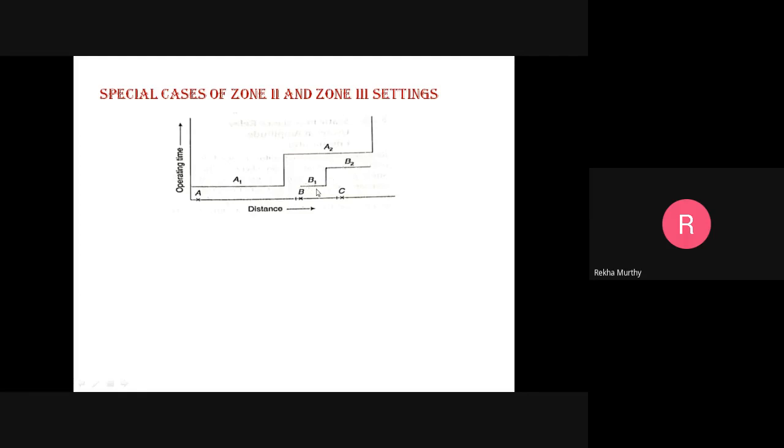the entire two sections under the zone 1 itself. So this is how the zone 2 settings has been done. So zone 2 is totally dependent upon the zone 1, which has covered the entire region. Okay, so this is how you can avoid the overreach conditions.